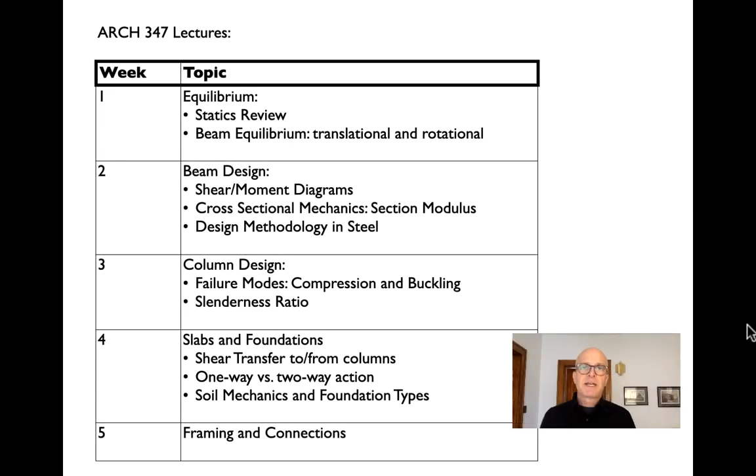So in this second piece of lecture one, we're going to talk about beam equilibrium specifically, and how translational and rotational equilibrium help us understand what's going on outside a beam, externally, to support it. We use that to figure out what we call reactions, the forces within a beam's supports that enable it to stand up. And then in week 2 lectures, we'll use what we learned to figure out what happens actually inside a beam.